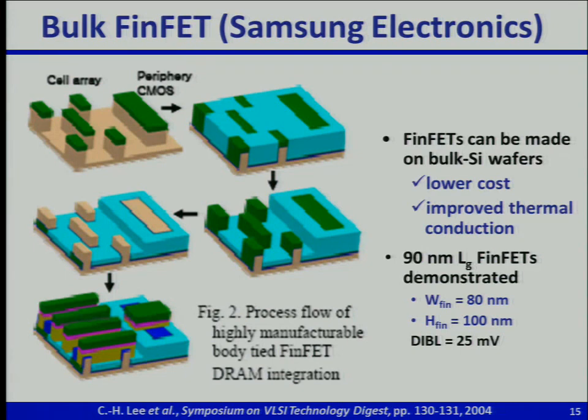Russ? The question is, why would you want to mix the two? Well, this is one reason why it's taken a little while for the FinFET to be widely adopted. One challenge with the FinFET is that in a circuit design, you would like to have some transistors conducting a lot of current, some not. In a memory cell, you might want to have the smallest transistor because it doesn't need to conduct that much current, but you want to save area to fit more memory into a certain chip. Other parts of the circuit, you want to operate faster, so you want them to be wider transistors to conduct more current, to charge and discharge capacitors more quickly.